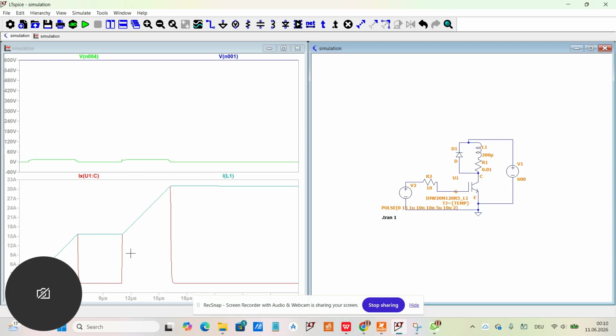And then in the second pulse, look at it here. When the transistor comes on, the current doesn't start from 0, you see. It picks back the current that was stored in this loop. It takes it from the 15 ampere from here and then starts increasing right up to 30 ampere, and then the pulse is done. Remember, we have just set this system to operate on 2 pulses, so it's a double pulse test.